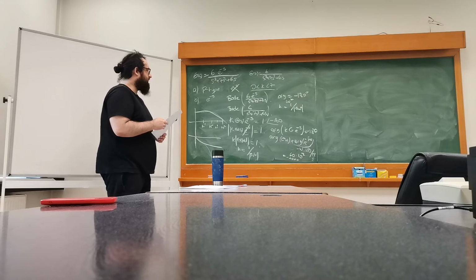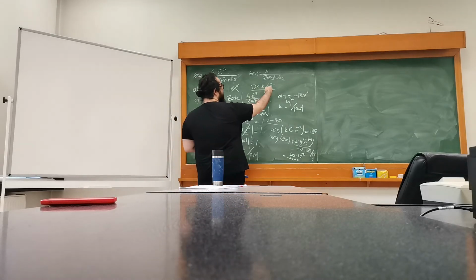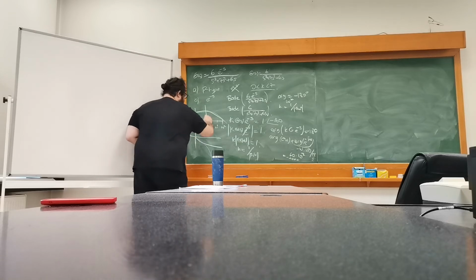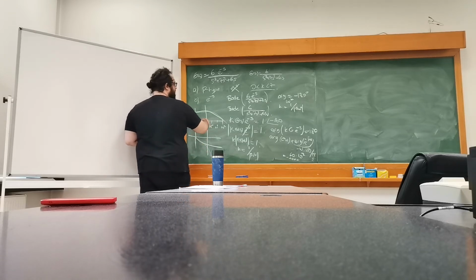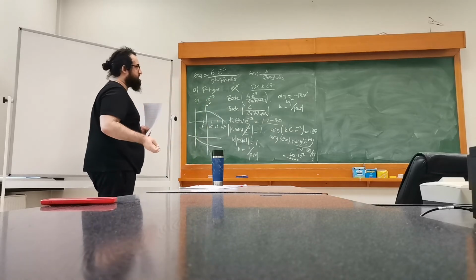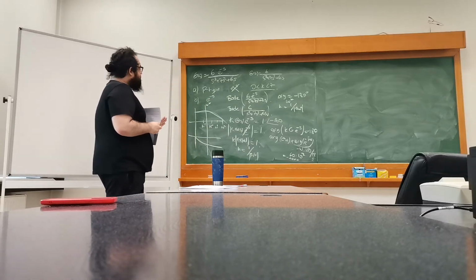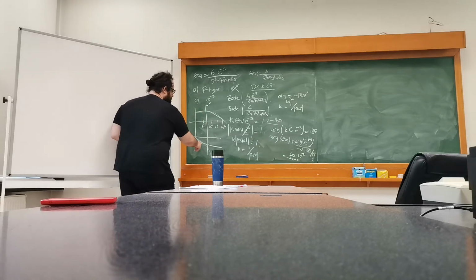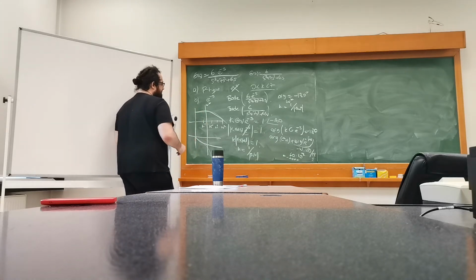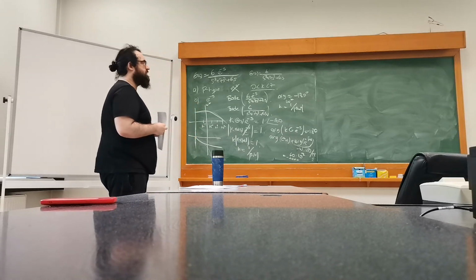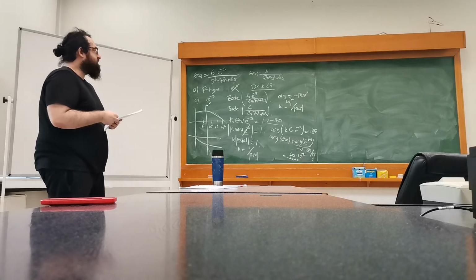For example, I know that this is between 0 and 7 without the delay. So if it's somewhere here, for example, if this is the line, the frequency that was for the non-minimum phase, for the minimum phase part, then I know that a previous frequency should be my concern because it goes down. So it will hit minus 180 degrees before the minimum phase part hits minus 180 degrees.